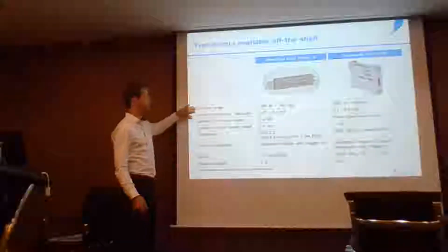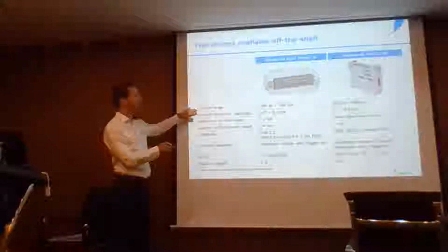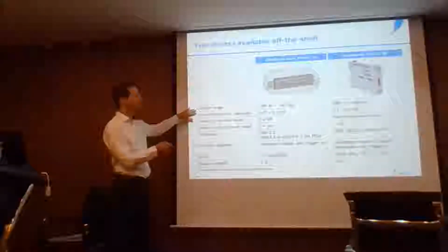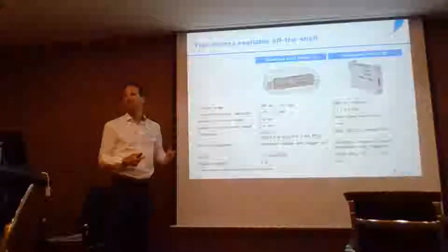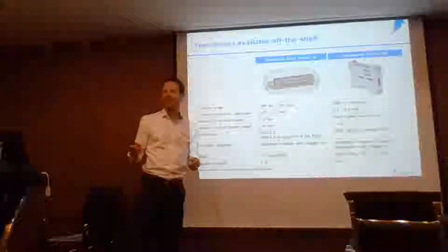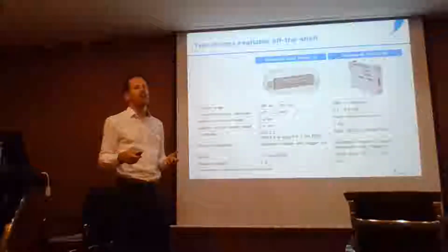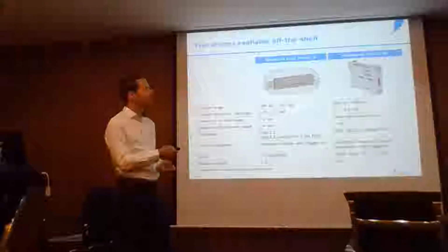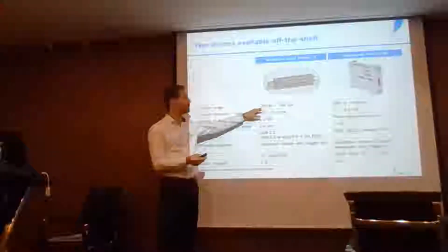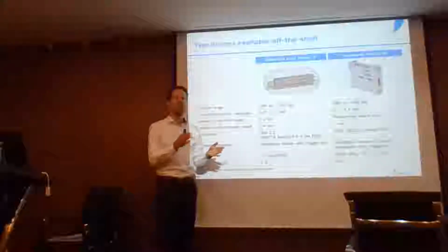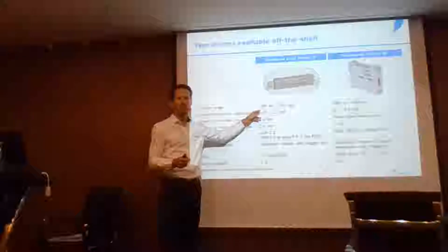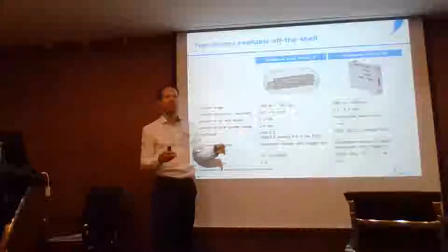So step by step, here we have a current range of minus 290 to plus 290 milliamps. This is enough for driving our lenses, although the EL16, for example, can take more current. So the EL16 could actually go to 400. If, for example, with our spec, we say minus 2 to plus 3 diopters, it's with a current range from minus 250 to plus 250.